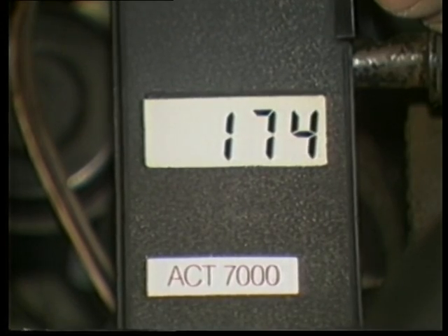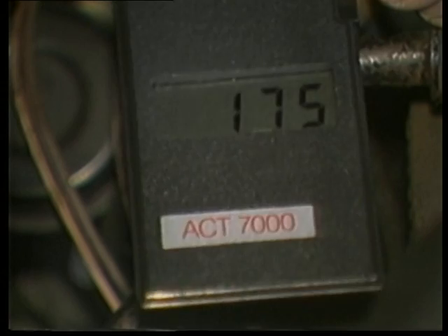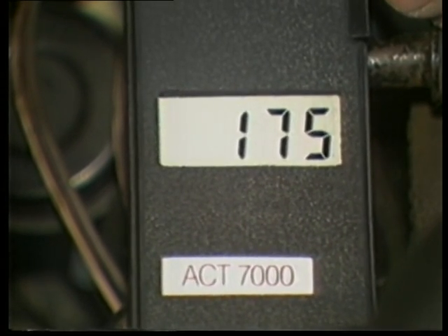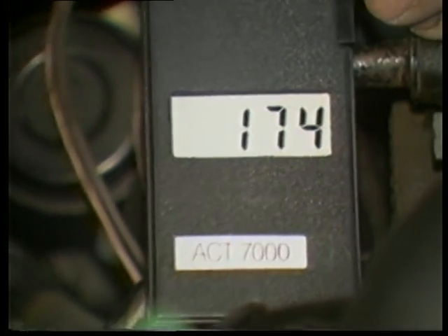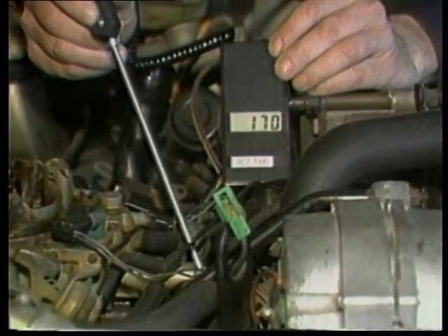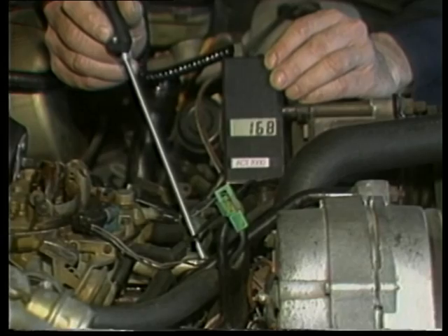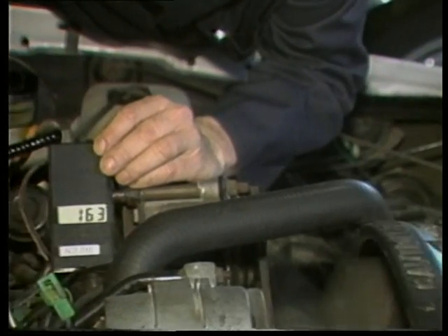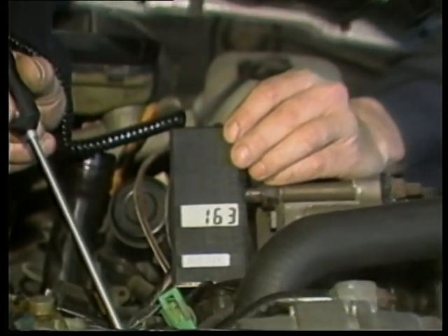While you're using your digital pyrometer, you might also want to measure engine operating temperature. If an engine is overheating or running too hot, it can upset air conditioning action. If the engine is running below normal operating temperature, it can keep the heater from working normally.